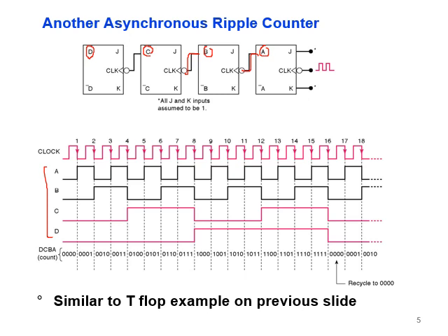Okay, you see the clock, this is falling, not rising, flip-flop, sorry, falling. You can see here it was 0, it became 1, and so on. 0, 1, 0, 1, similar to the table in the previous slide, if you remember. Now, when we have 1 on A, which enters as input to the next, then toggle will occur and we have 1 for the next two steps. When 1 changes to 0, then it changes to 0. When 1 changes to 0, it changes again. You see the toggle, whenever we have a toggle here.